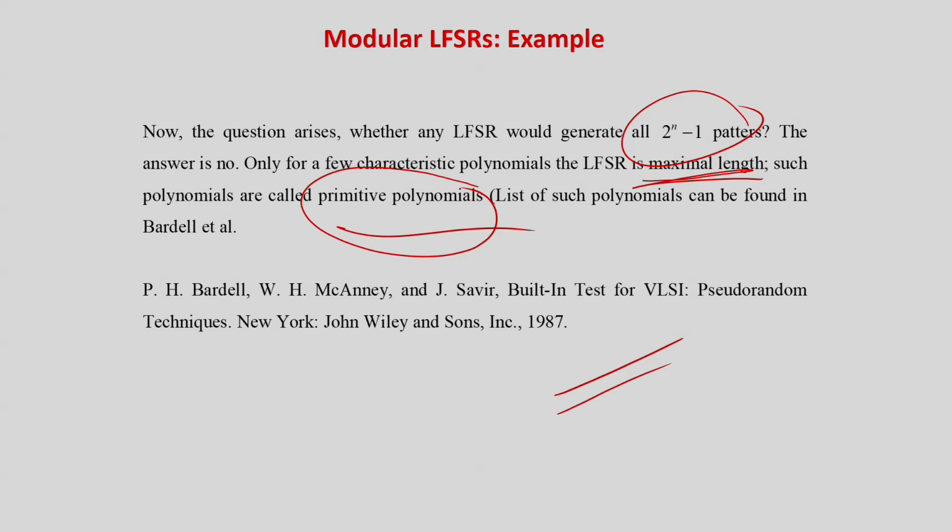So just by your requirement, you look at the characteristic polynomial available for different ends and you select it. Test engineers are basically not directly involved in the theoretical proofs; rather, they know the theory works. So you select the required ATPG vectors which you know will be generated by this LFSR. You can select a primitive polynomial, and for certain cases if you do not require the entire spectrum of values to be generated, maybe only 4 or 5 different patterns, then accordingly you can put the XOR gate and design the LFSRs.